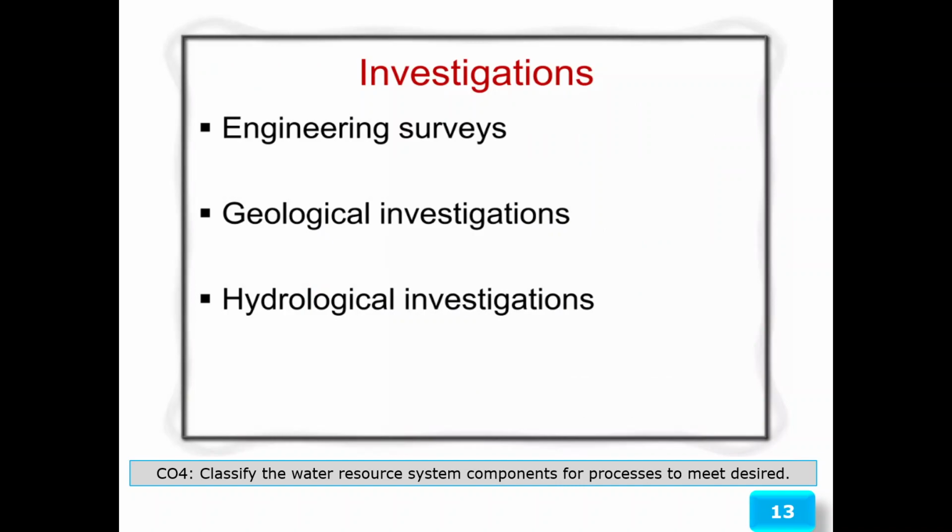Before starting the reservoir, what are the investigation steps we have to make? First of all, we should take the engineering survey. We know very well what is meant by survey: the art of determining the relative positions of earth features and the environment. The second one is the geological investigation of the bedrock surfaces in this area, which is applicable to us, so we have to do the geological investigation.